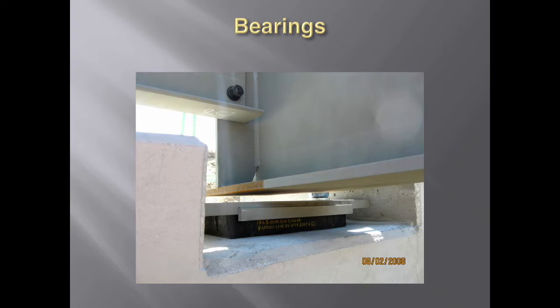What we ended up doing is go back and jack the bridge, pull out the bearings, and put the correct bearings in the right place. The other thing, like Mark said, is the location, also identification of the bearings. So if there is a failure in that bearing, we can go back and locate all the test reports and everything on this bearing for the marking.